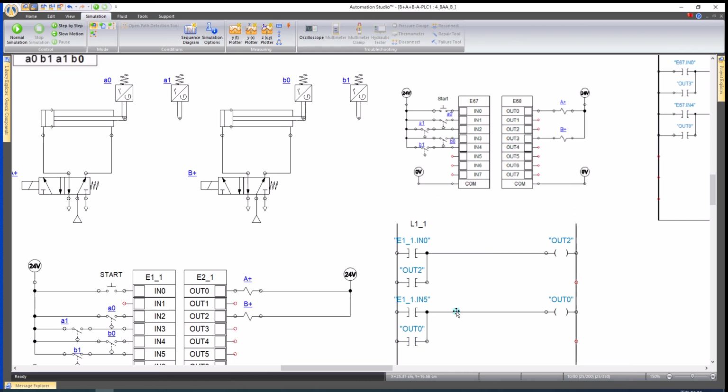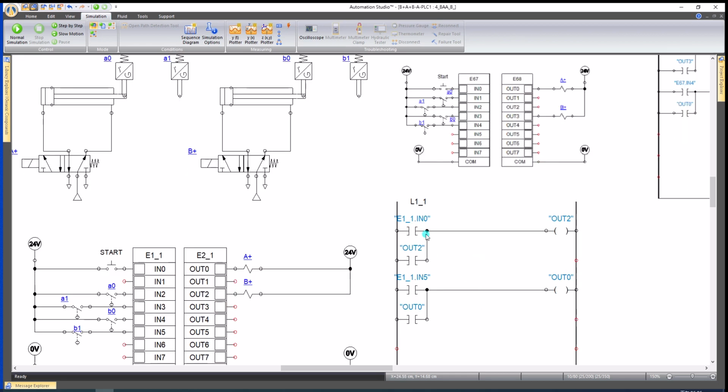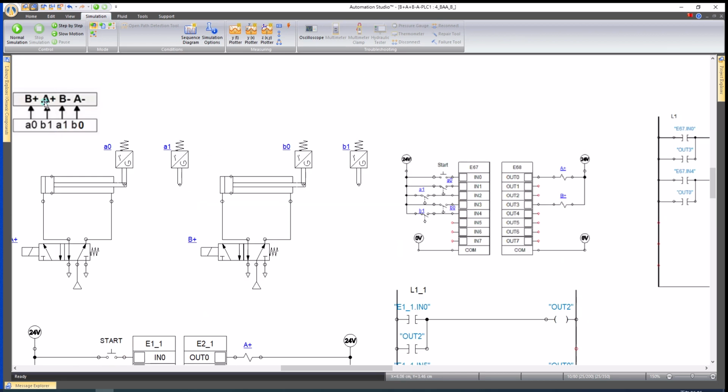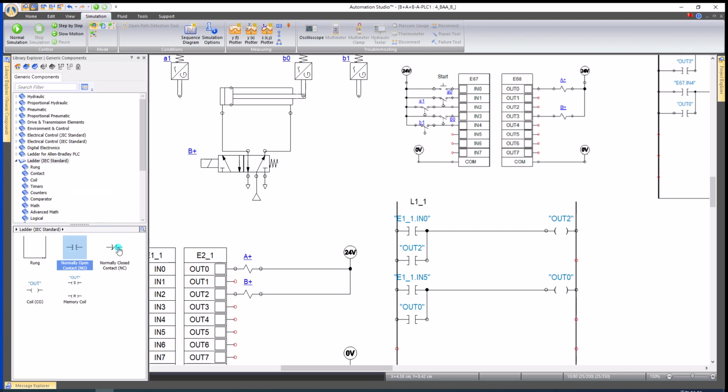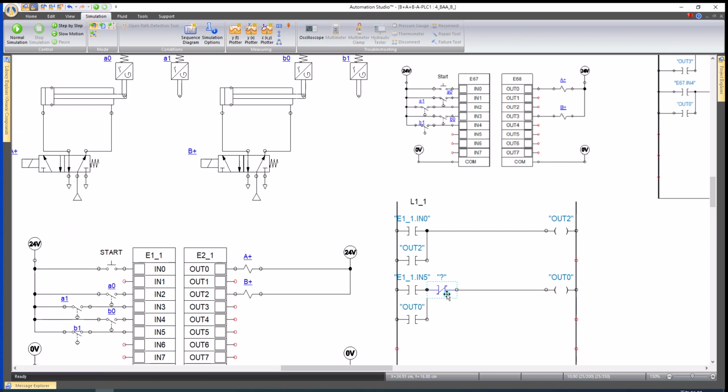Okay, right now on this stage we always keep everything in the right hand position, but once you reach this one, remember A plus, when you reach the A1, because B plus and A plus. Once you reach A plus, you need to trigger the B coming back. So why should it trigger the B coming back? We call it normally closed.